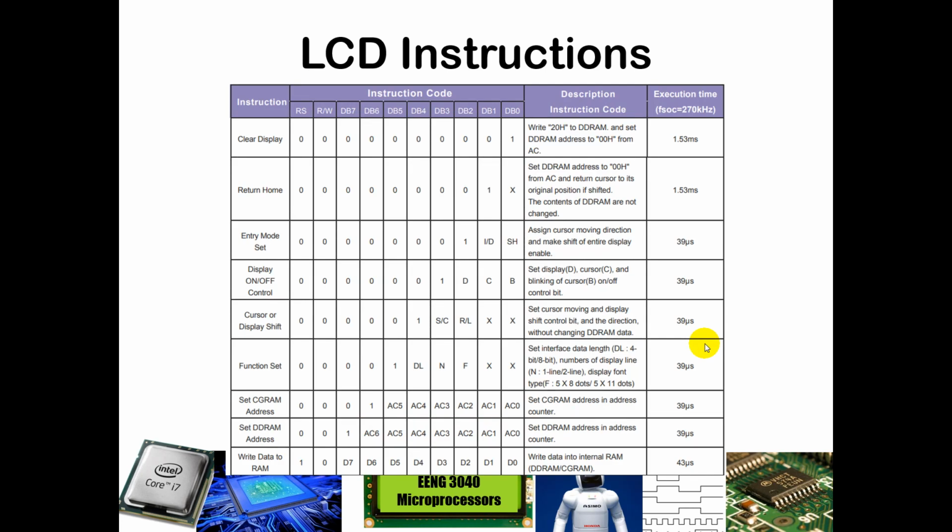There is a fairly limited instruction set for the LCD. These are instructions in terms of not the C code necessarily that we're going to be writing, but what needs to be set up on our instruction port, and then what we would put in RS and RW in order to clock in these various instructions. We will be using C code to provide these, but largely we have to set these up as voltages on the pins using our external I/O expander. And so as you see here, we can clear out the display.